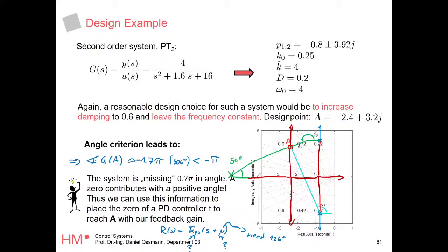So what's always going to happen is, if you change to 2 pi or minus 2 pi or minus 4 pi, you will destabilize the loop, and this is actually what's happening here. So I would encourage you to always go to minus pi, plus pi, or 3 pi, 5 pi, and so on, right? Because most of the time, the constructed problems for the exam will end up with a stable loop.